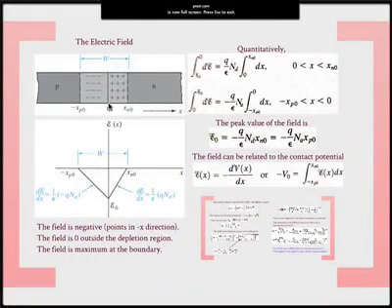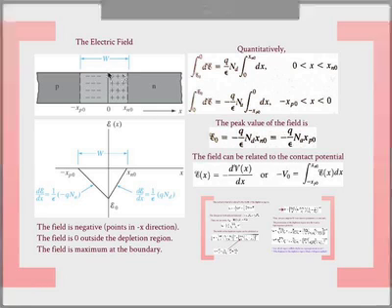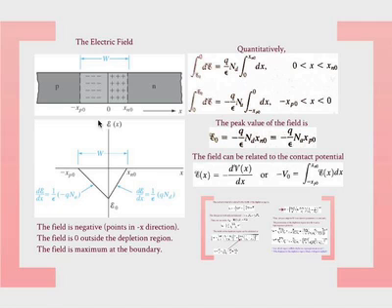In other words, we were able to calculate how the charges are distributed here in the transition region, or the depletion region. What is the field that develops across here, right? And we applied Poisson's equation, and we are able to explain all this fairly accurately. We make the assumption, which will become much more important today, that these regions outside this transition region are neutral. There are no charges. If there are no charges, of course, there's no field. Okay? But inside here, we have specific charges which are basically related to the uncompensated ions, the donor-acceptor ions.